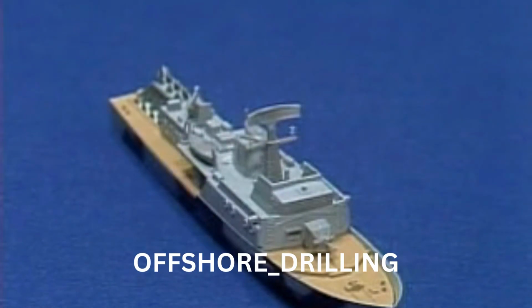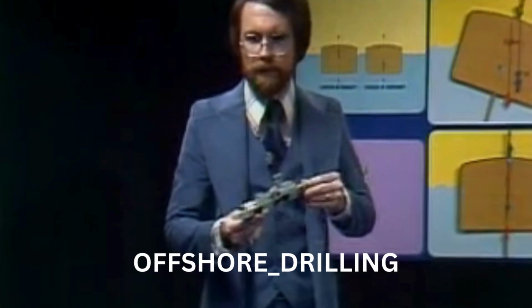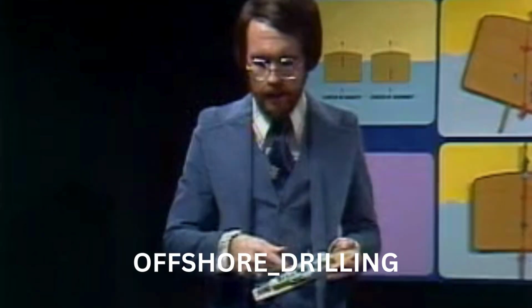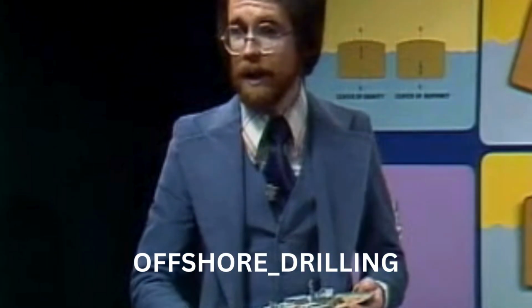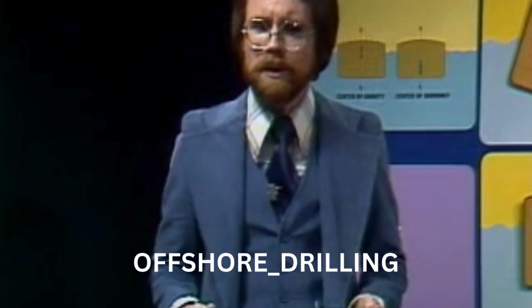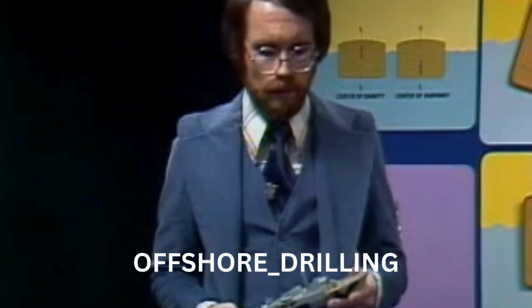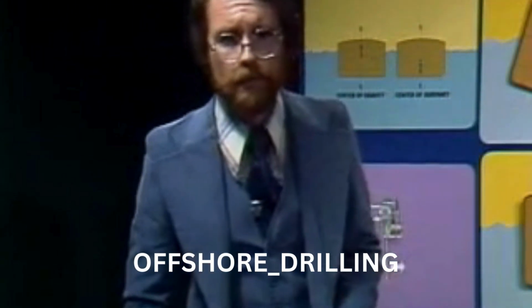So far, we have been concerned with transverse stability only. This is the stability of a ship from port to starboard or from side to side. As you know, the port side is the left-hand side of the vessel when looking towards the bow, and the starboard side is the right-hand side of the vessel when looking towards the bow. Right now, we will not worry about longitudinal stability or a vessel's stability from bow to stern until we get into the subject of trim.